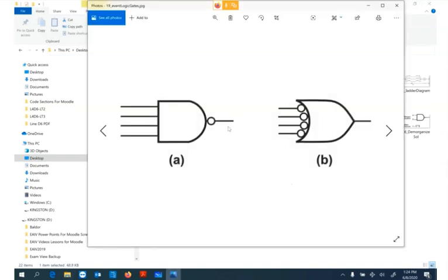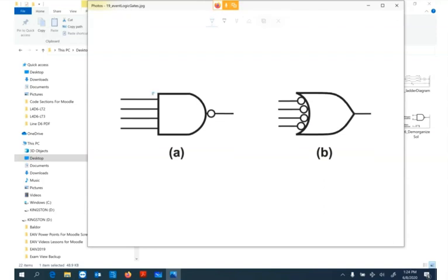Another example, a 4-input NAND and the DeMorganized equivalent. Basically, inverted all the inputs, and because this one's already inverted, two inverts make a normal. Of course, the sign was changed to an OR, as you can see over there. Kind of simple to do, just have to get your head wrapped around it.